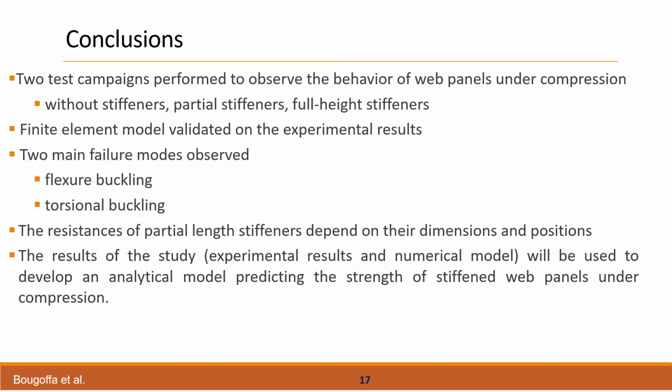As a conclusion, two test campaigns were performed to observe the behavior of web panels with and without different configurations of stiffeners. A finite element model was validated on the basis of those tests. Two failure modes were observed, flexural buckling and torsional buckling. The resistance of partial stiffeners depends on their dimension and position. This aspect needs to be analyzed further.